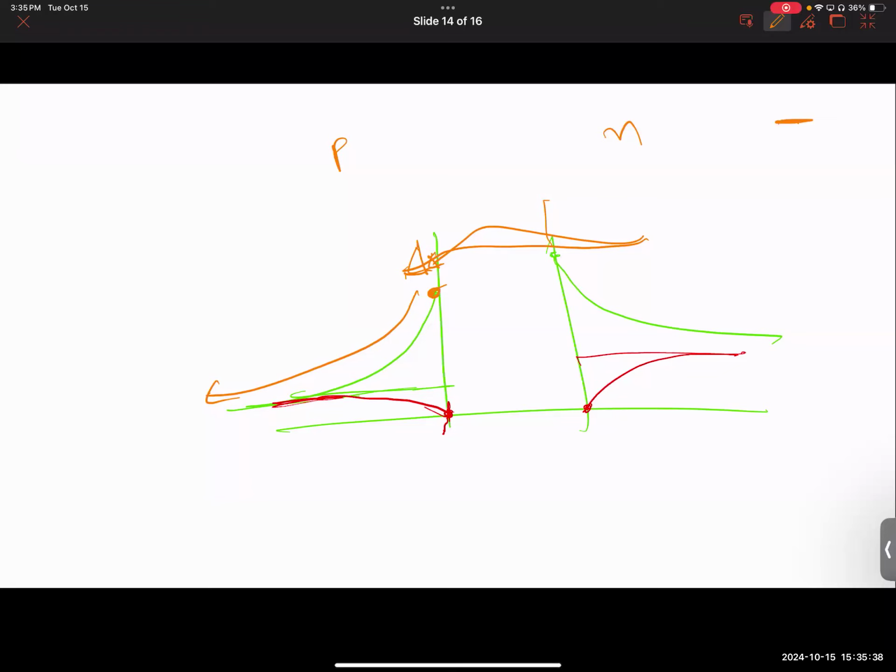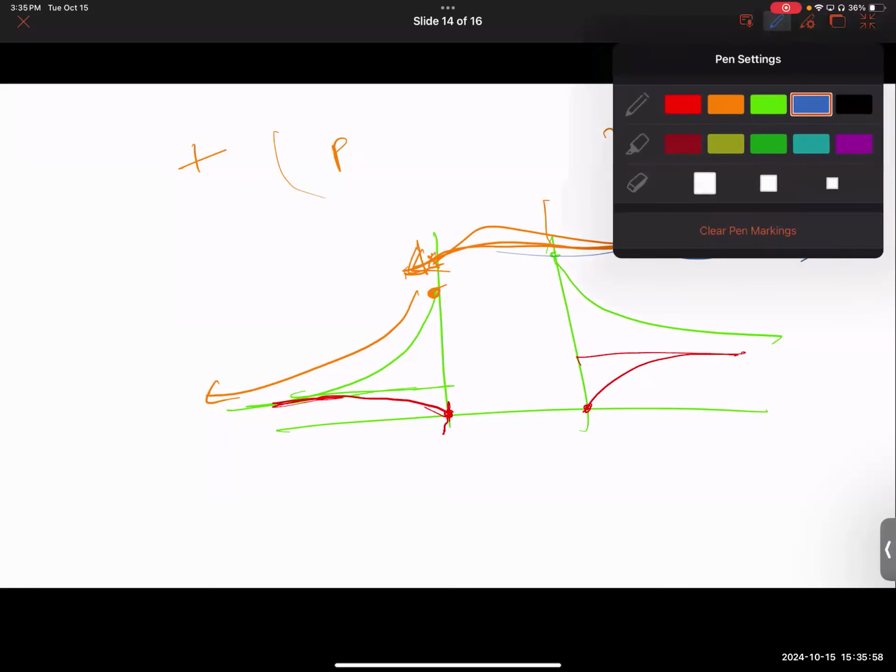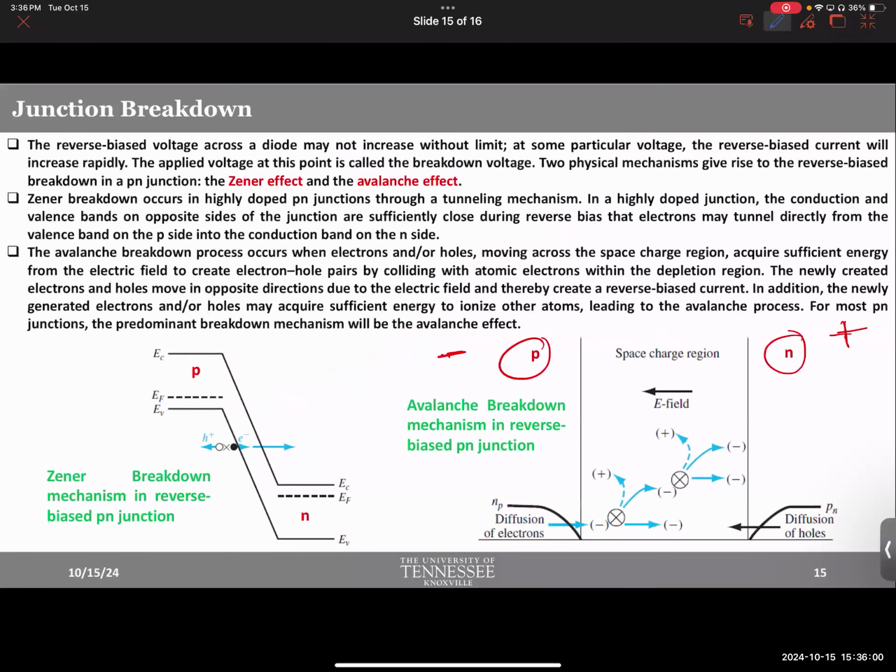Because they were repelled by the forward bias. Say, when you apply negative to the N-type, electrons are repelled and they go to the other side. But when you apply reverse bias, meaning you apply positive here, electrons are never repelled. Basically, they don't want to go to the other side. They're attracted to the opposite direction. Making sense? So basically, that's why these distributions are exactly opposite. That's what you see here. Just wanted to quickly explain this.